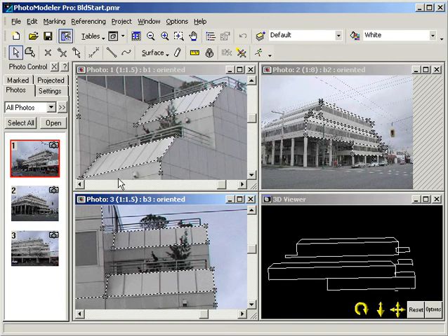We click the Edge tool from the toolbar, and the cursor changes to Edge mode. We move the cursor over to this edge of the patio, click once at the top and once at the bottom, and an edge is created. The edge mark looks different from a line mark in that its endpoints are small circles, and its line has a slightly different pattern. An edge is not a line connected by 2 points. An edge is a single entity with 2 endpoints.